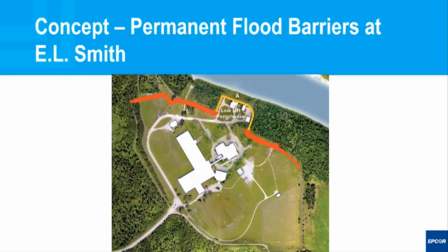So what those barriers could look like, we have a slide showing here. Again, in blue, you can see where the North Saskatchewan River normally is. That section labeled as A was how high up it got in 1986. And then across the entire site, it could come at 1 in 500. What's shown in orange are the embankments that we have conceptualized for right now. What's shown in yellow are the flood walls that we have conceptualized.